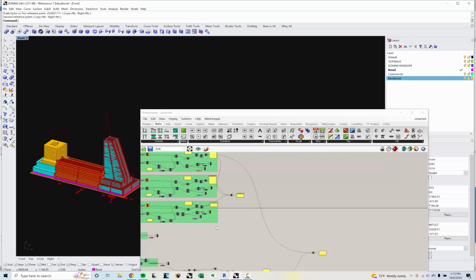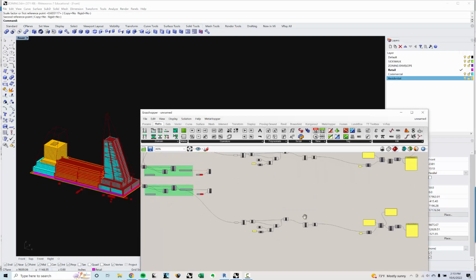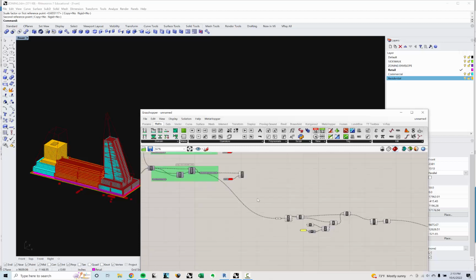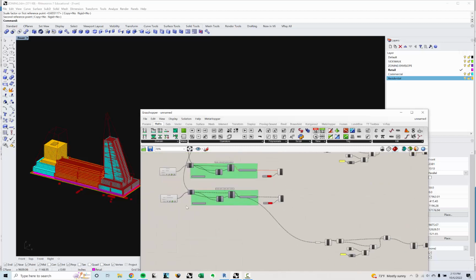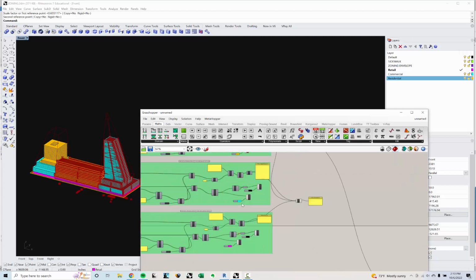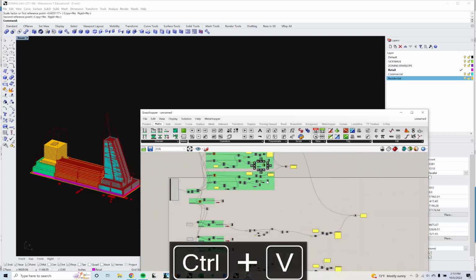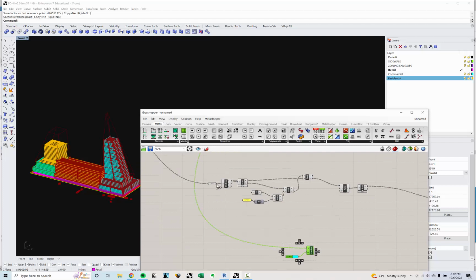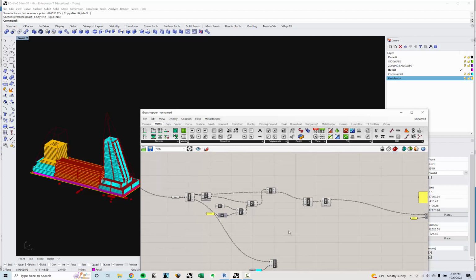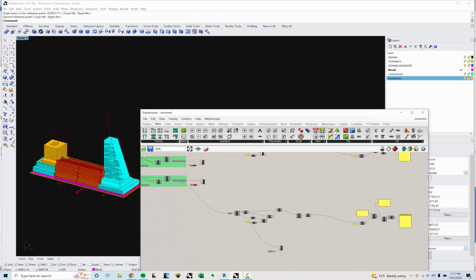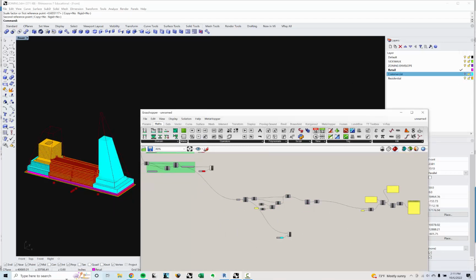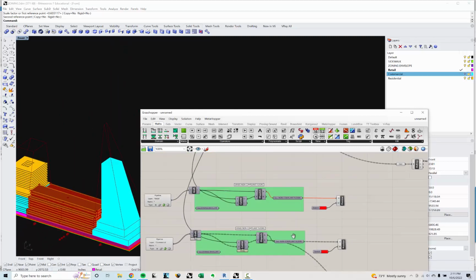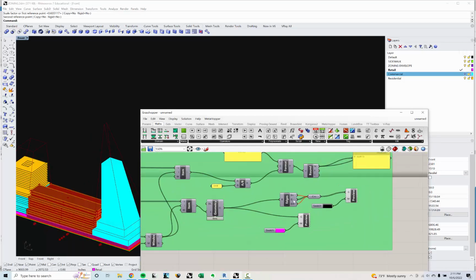If you wanted to give it a little bit more cleanliness, you could do a custom preview on this geometry, which is your compliant geometry. If this is commercial, just grab your little custom preview component here, bring that down, and plug this geometry into there. Turn off all this preview, and then if you were to hide this layer, you're now only seeing your compliant geometry previewed. You could use that little edges trick as well if you wanted to. Same thing that we did up here.